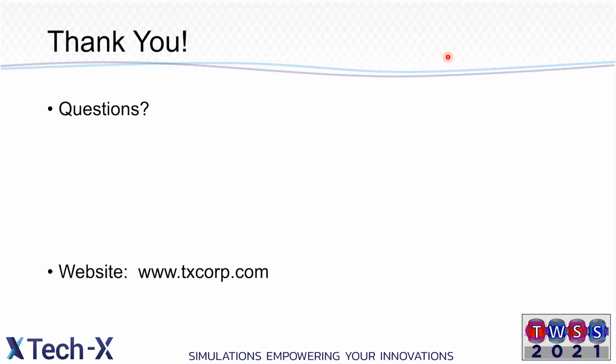We do occasionally ask what would happen at liquid nitrogen temperatures. That would take us from phonon to impurity scattering and change our mobility. So we do occasionally change our collision frequency to represent cryogenic situations. But it's really just that single parameter that represents all of that behavior.